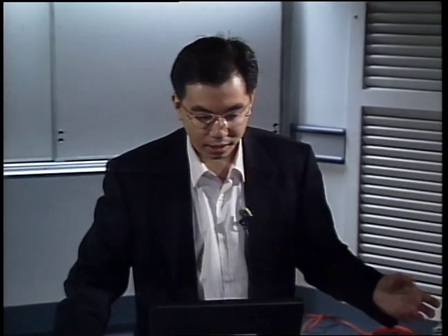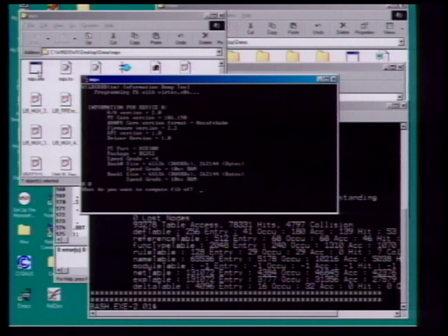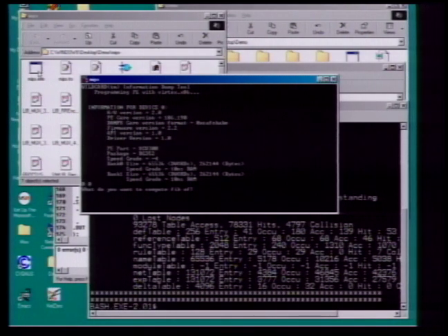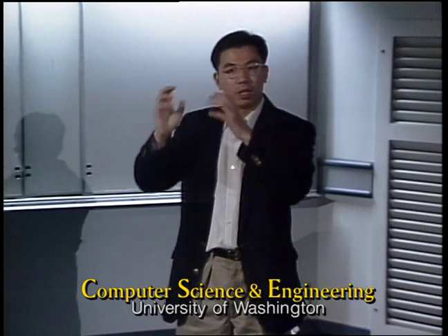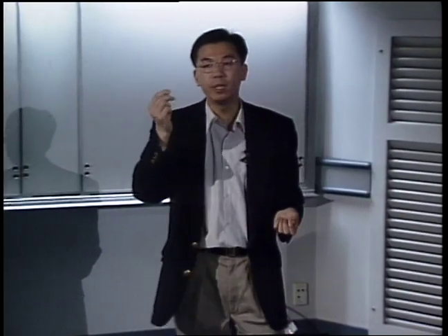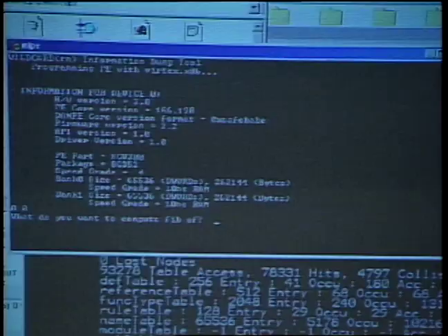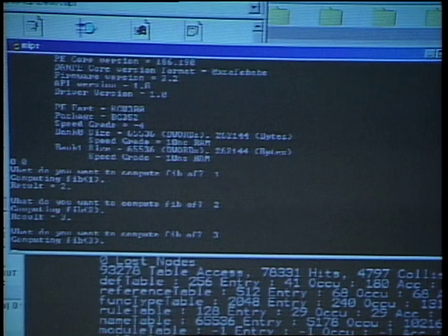So now I have generated the synthesizable Verilog. Again, I can download the configuration onto the FPGA. This larger design will take about half an hour in the Foundation tool. But what's happening now is I downloaded the configuration for the MIPS processor onto the FPGA, and we're going to use the FPGA as an emulator now. What has also been downloaded is the actual MIPS binary for the Fibonacci program. And now we can run the FIB program on the emulated processor.